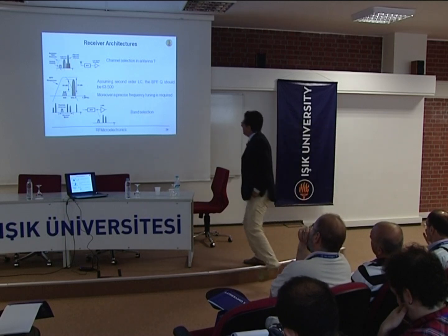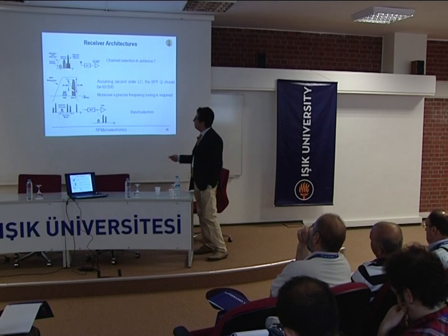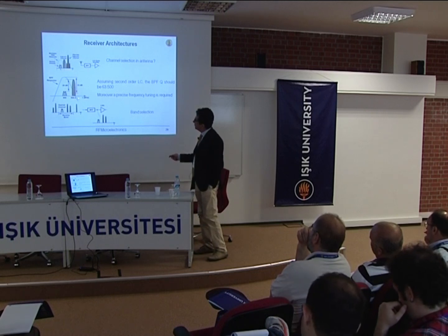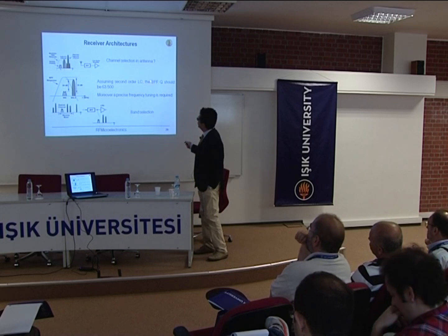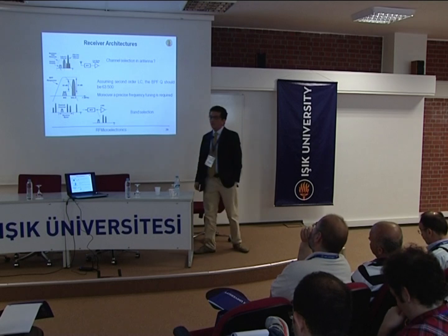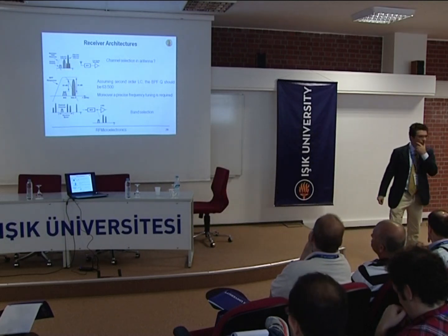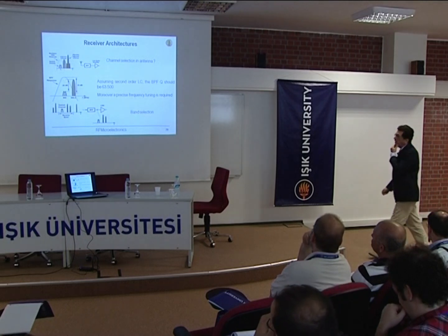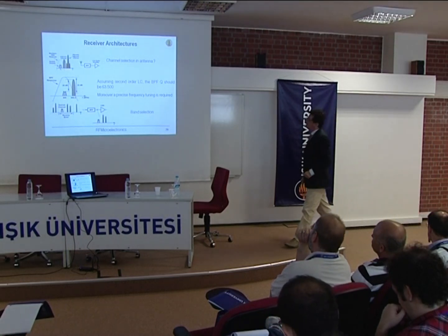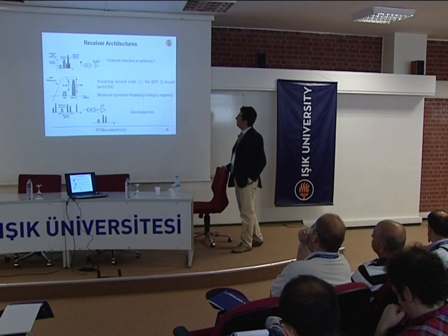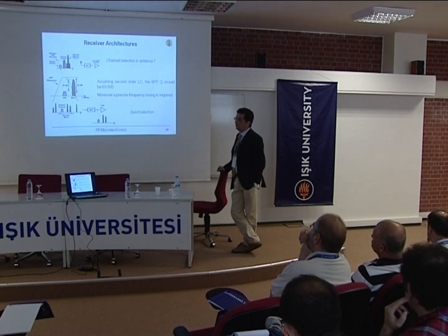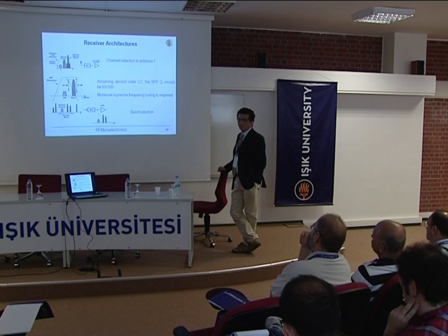So if you make some calculation in order to be able to reject this adjacent channel by this quantity with an LC filter, you realize that the bandpass should have a quality factor of around 60,000, which is not possible, not only in an integrated fashion, but not even with a really high quality off-chip discrete component.